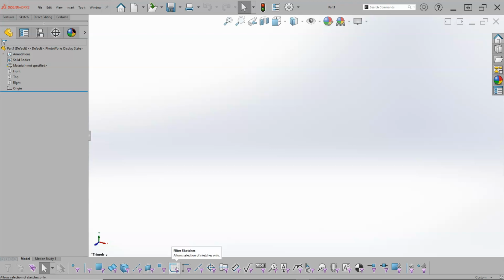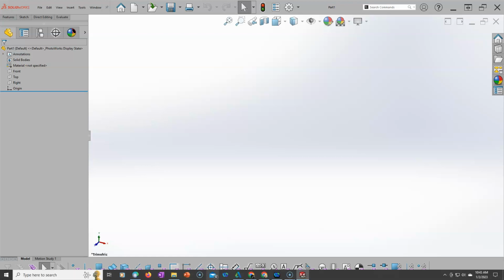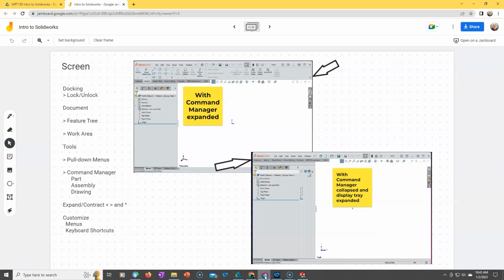So right now, filtering for, let's see if we highlight these, our standard Windows shows me the short key. If I accidentally hit an X and filter for faces, or an E and hit for edges, then I can glance down here and see that that filter is on, and well, it gives me an indication that I've kind of locked into that item.